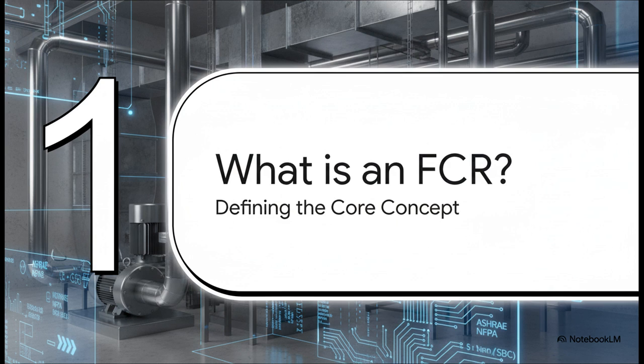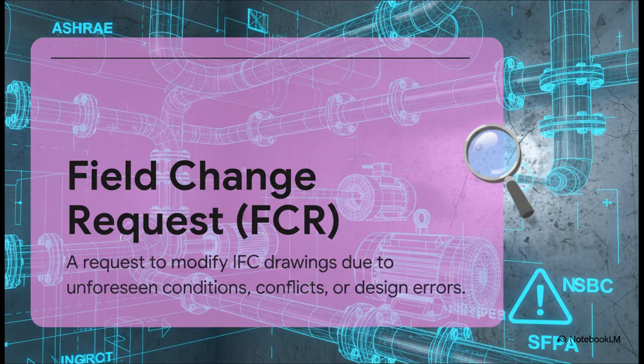Any great interview answer starts with a really sharp, accurate definition. So let's nail this down. A field change request, or FCR, is the official, formal way you deal with the unexpected. This isn't just a quick email or a chat with the foreman. Nope, it's a structured, documented request to change the official construction drawings. We call those the IFCs, because something in the real world doesn't match the plan. Think of it as your formal problem-solving toolkit.